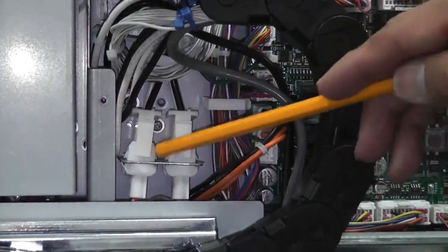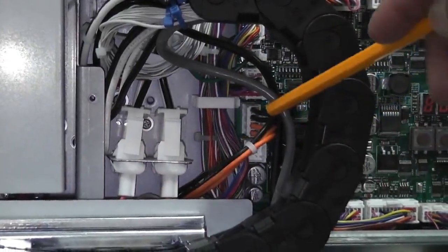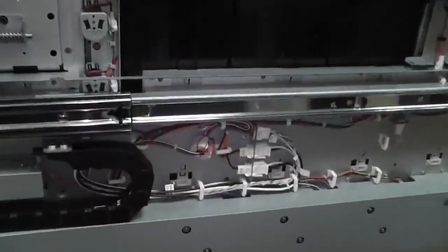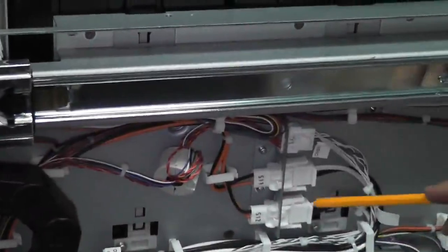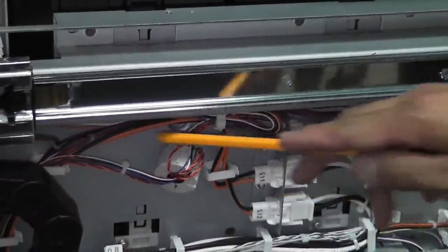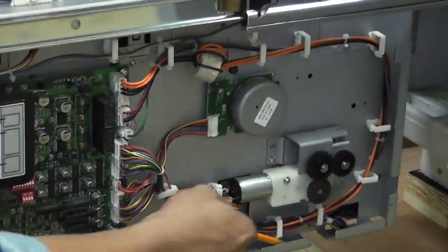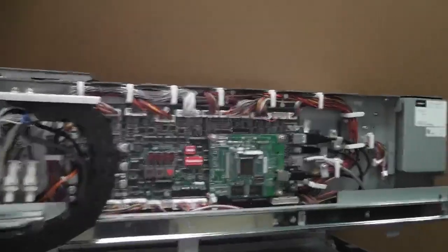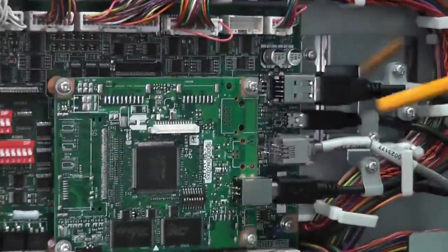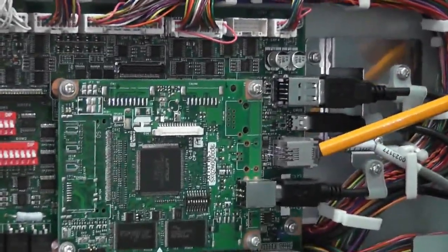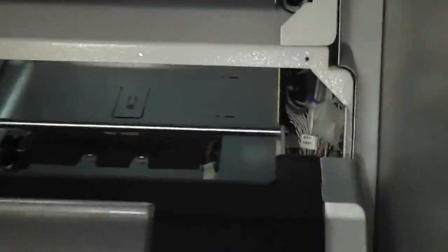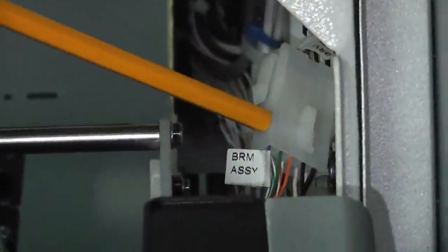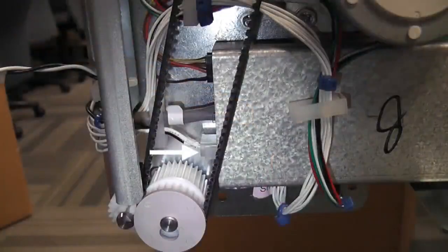There are two 24-volt DC cables connected to the upper module control board and another two 24-volt DC cables connected to the lower module. These are routed to the lower control board at the left side of the BRM. The upper main control board controls the BRM shutter via the I2C cable, which leads to the shutter assembly, and is connected to the shutter PCB.